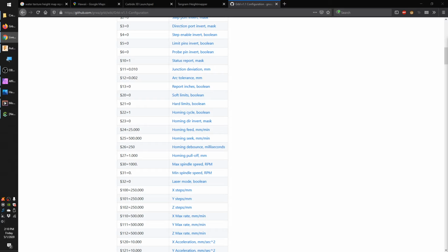We'll see. I'm going to import an arc in DXF format into Create. It loses definition. The arc is no longer smooth. So DXFs can be tricky because there's a lot of different formats and compatibility things. If you can convert it to an SVG first, that's usually better.